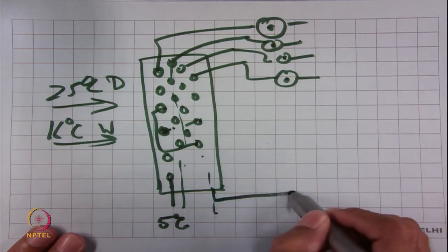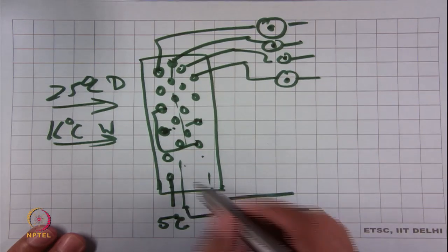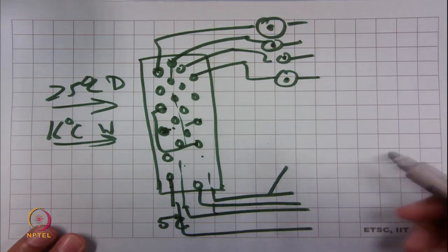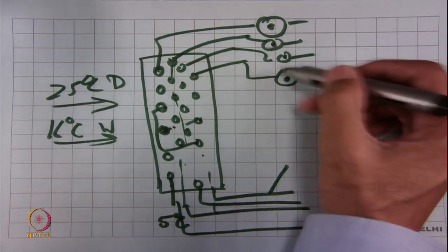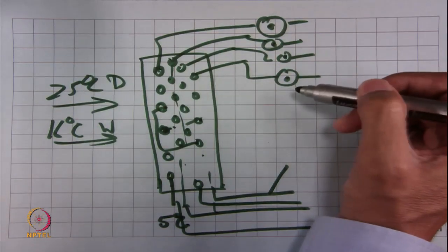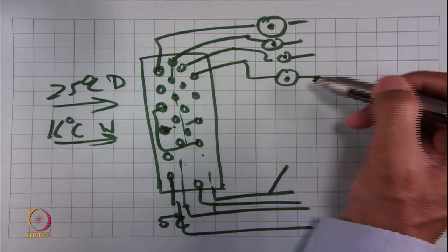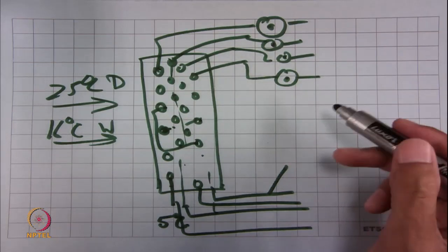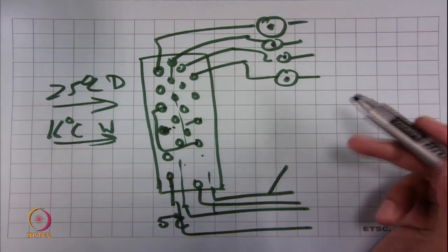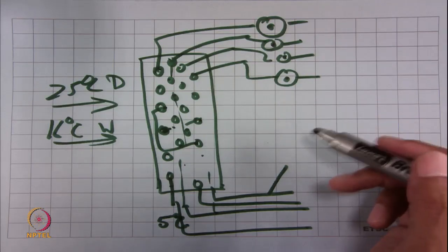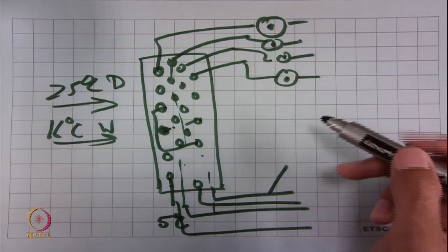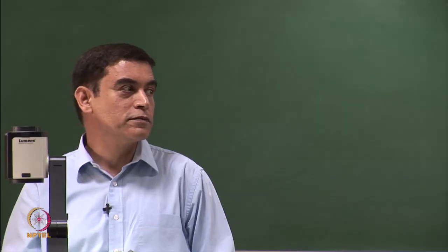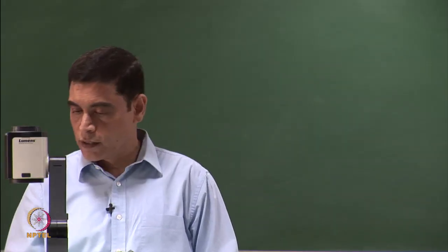The feed to each of these circuits was again through a capillary, and it was possible to resize the capillary, which is the expansion device, so that finally there is a balanced load, and this was a purely experimental approach to getting to a balanced circuit. So, this is one part of the design, and it also illustrates that when we do not have the best analytical software, we can still achieve the objective of a design by looking at some very fundamental and direct ways of measuring the performance of a subsystem. A subsystem here being the evaporator coil.